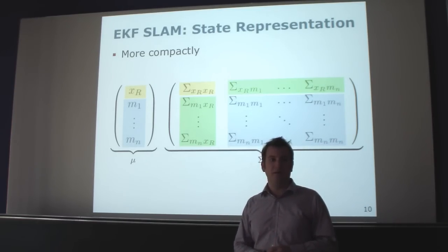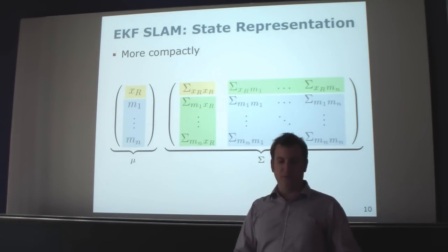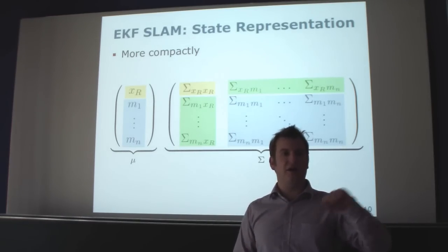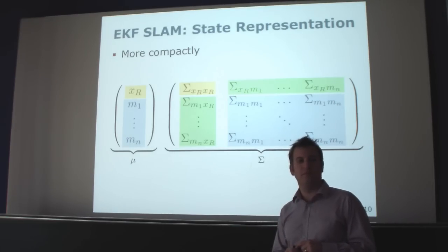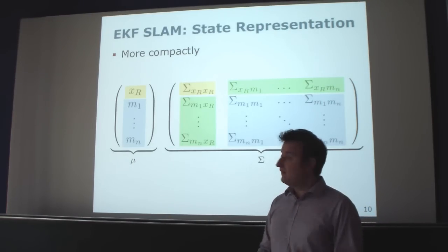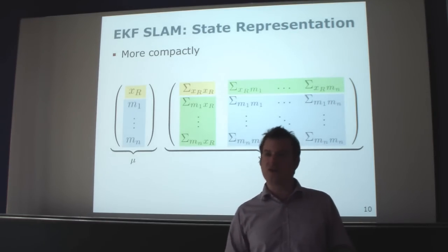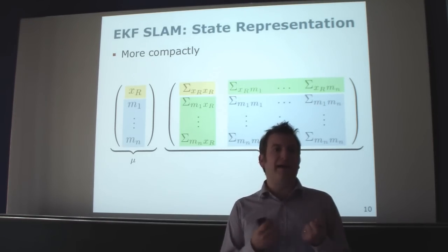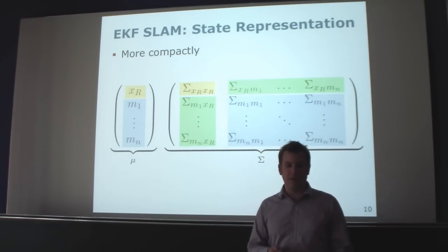How do we calculate the single elements of this? We will come to that in a second. So you will see that. So we go through all the different steps of the EKF, and we will actually come to all those elements. I'll tell you how you actually compute all the individual elements. There is a function which is the robot moving, and then you do some partial derivative on this function. So the updates of all those elements is just done using the equations in the EKF algorithm. There's no other black magic we put in there. Everything results from applying the EKF equations.